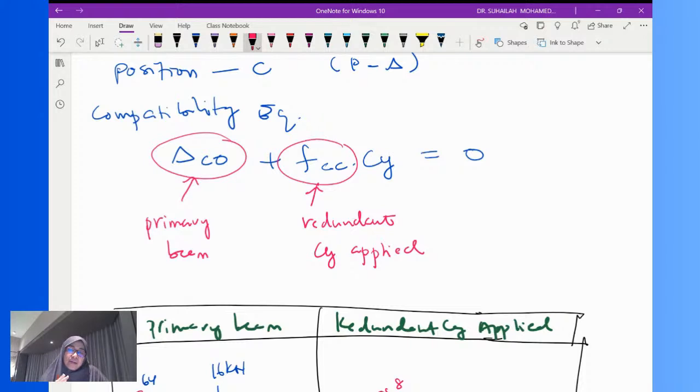in structural analysis, there are 3 main steps when we analyze a structure. First is reaction, second is internal forces, third is displacement. We calculate reactions from external forces. We calculate internal forces from reactions, and the moment equation that we write is part of the internal forces. And then we calculate displacement based on internal forces.